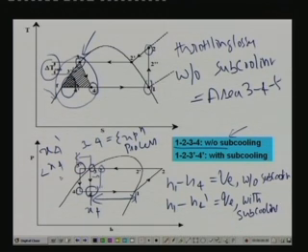It also has practical benefits, as we shall see later when we discuss evaporators. The vapor at the inlet to the evaporator practically does nothing. That means it doesn't take part in providing useful refrigeration effect as long as phase change is going on, but it has a negative effect because it increases the pressure drop through the evaporator. Normally, the smaller the amount of vapor, the better for the evaporator. By subcooling you are reducing the fraction of vapor at the inlet to the evaporator, which will reduce the pressure drop in the evaporator and ultimately result in better performance. So subcooling has these three benefits, and it is very much desirable.